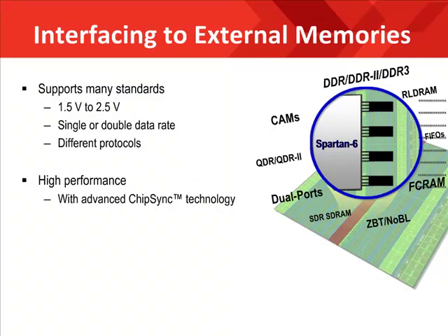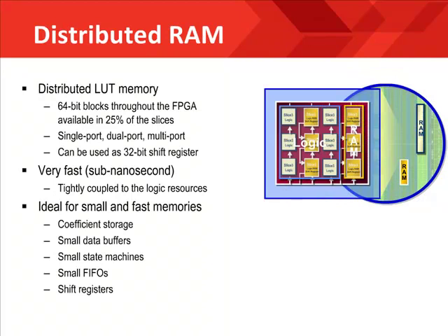As I mentioned, the MCB and the soft memory controllers supported with the MIG are designed to build a number of different types of memory controllers. These can support a number of different I/O standards, single or double data rate, as well as different protocols. This is accomplished with the aid of the SelectIO functionality, which allows direct connection to a range of different I/O standards. This assures high performance and design reliability since the pin assignments are often pre-optimized by Xilinx experts.